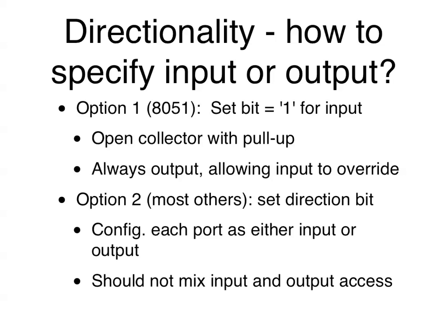Now, as an I/O port, that means the port can do input and it can do output. But how do you know when it's doing input or output? Well, there are different ways to do this. The original 8051 way, what I call option 1, is you are always outputting, but you set the port to 1 when you want to input.